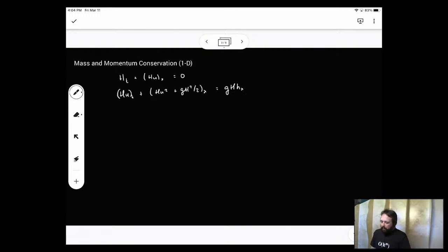And what we mean by having momentum conservation is if you were to integrate the momentum equation over all of space, what you should end up getting is a statement that basically says the momentum is only coming in from the boundaries, and same thing with the fluid volume as well. And sure enough, at least on the fluid volume side, it's pretty easy to see if you were to do an integral over your model domain, and here is just in the x direction.